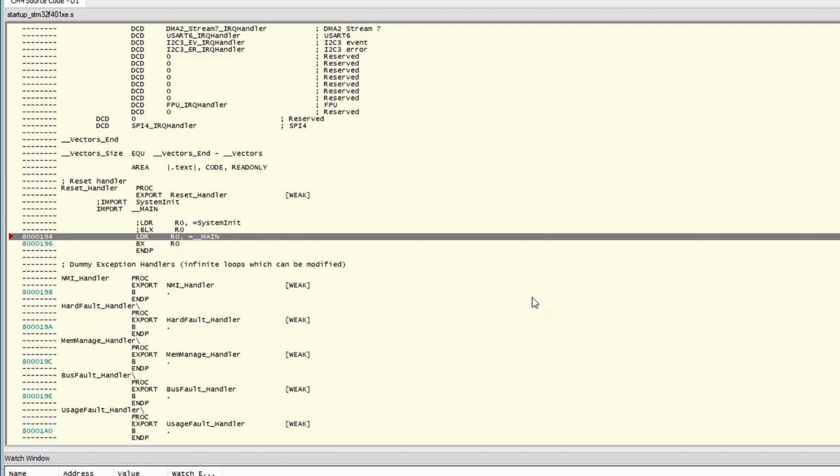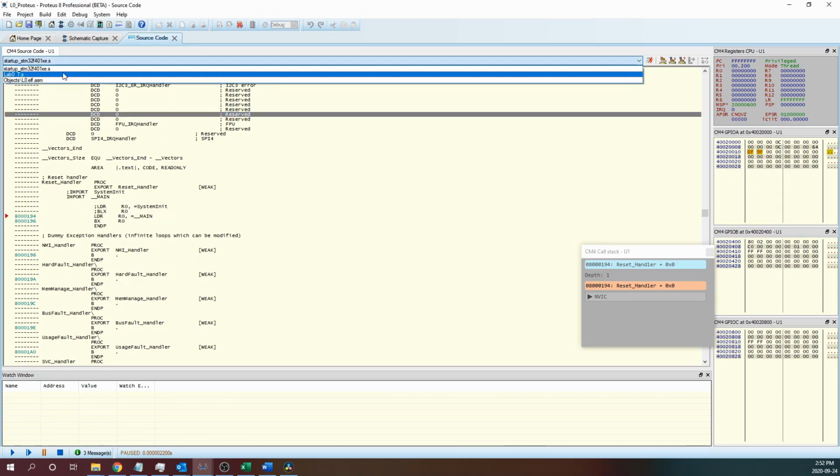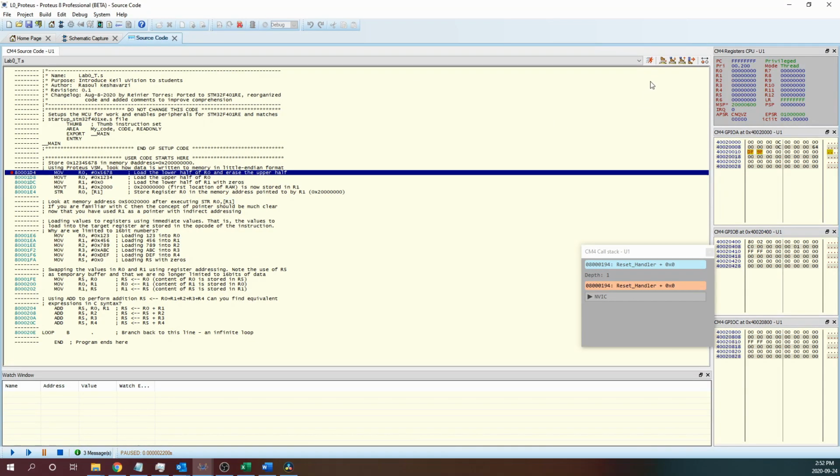The debugging session can begin after you set at least one breakpoint on the line you want to pause the simulation. Let's put the breakpoint on the first line of our code. To set up a breakpoint, you can double-click on the line or press F9. A full red dot indicates an enabled breakpoint. If you keep clicking, the breakpoint will change to an empty dot indicating a disabled breakpoint. Keep clicking to remove the breakpoint. Let's put the breakpoint back, and we will be ready to start the simulation.